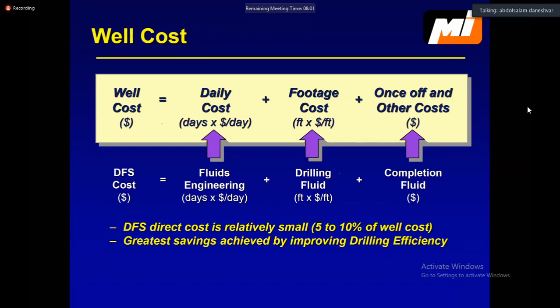Good. Now, the biggest issue is about the shale formation, yes? In terms of hole instability it is shale, because it collapses, the shale deteriorating on us. On the other hand, we have dolomite and limestone formations, but we have problems with losses, mainly total losses in those 2 formations, dolomite and limestone. That means, this is for the beginners, when we pump the mud inside the pipe, when it comes back to the annulus, there are big vugs and caves and fractures. It cannot come back to surface. So most of the time we drill blindly. That means our mud cannot return to surface because of big fractures in dolomite and limestone.